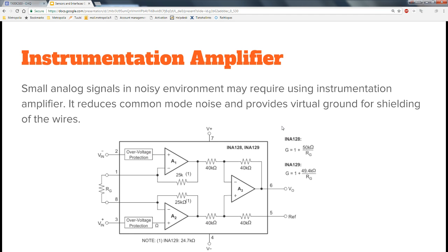You have to first have very good insulation, but not just that. Since you have this sensor and then a wire, or actually a wire pair, and then you have this electric field, you will have some sort of electric noise on both lines, in the same amount. So basically, in addition to this electric signal, what you are measuring is UN plus EN.